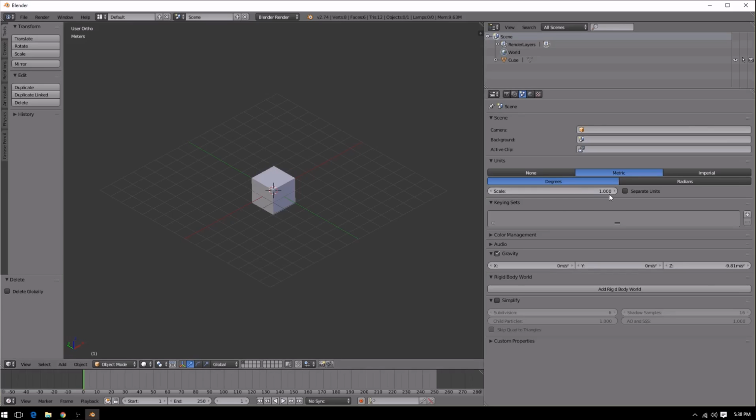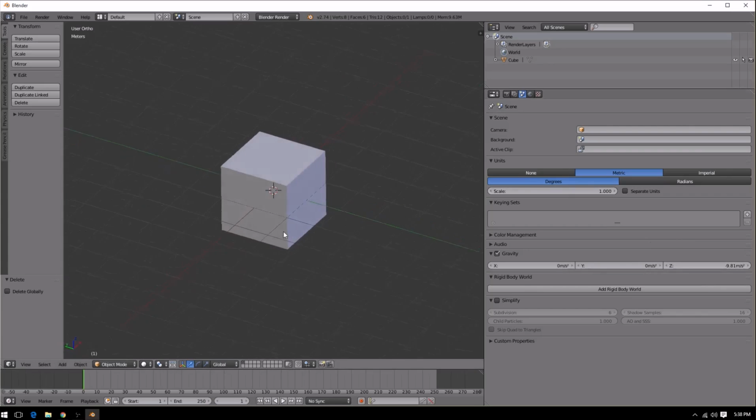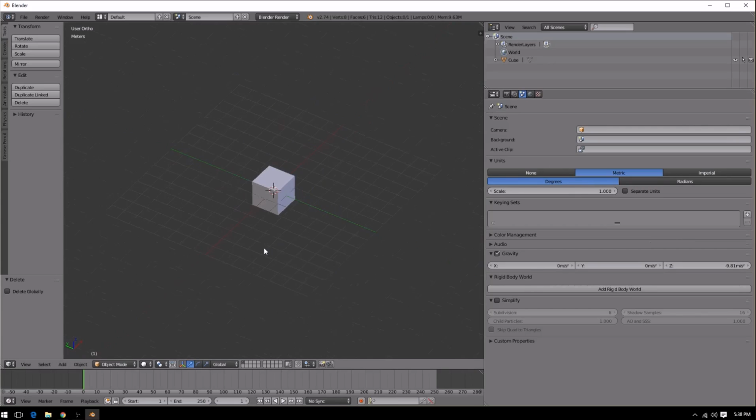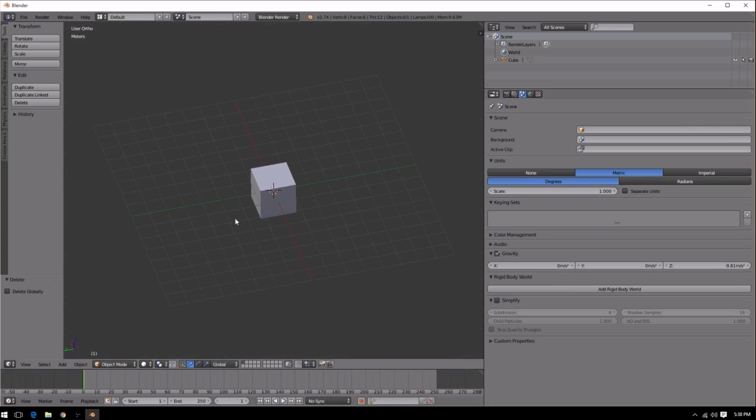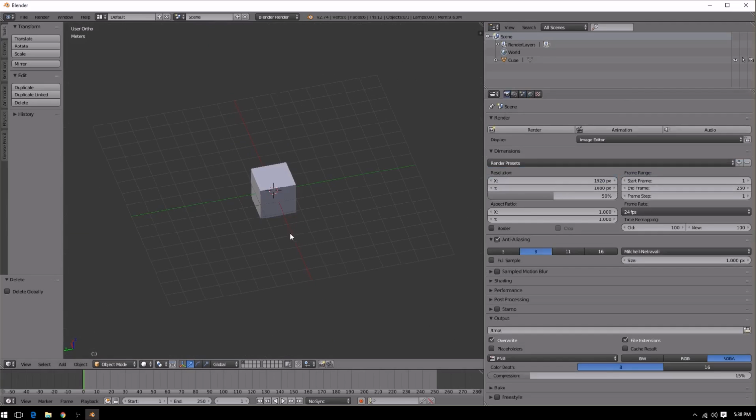I think if you click this scaling, and you might change this to 8, that could actually be a 1 block to 1 block ratio within Cities, but I'm just not versed enough with that yet to be confident that's what it does. So I'm going to skip that piece, but you might want to fiddle around with that later and see if that actually will make it a 1-to-1 kind of thing. Since we don't have that set up, and right now we have it set up for 1 block is 1 meter, I'm actually going to multiply everything by 8 so that we can get the correct plot size within Cities.